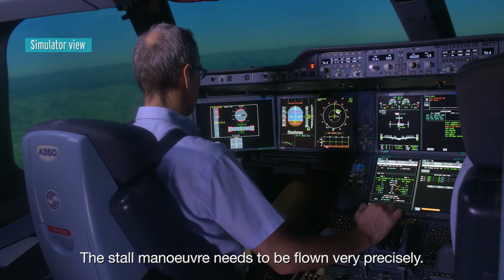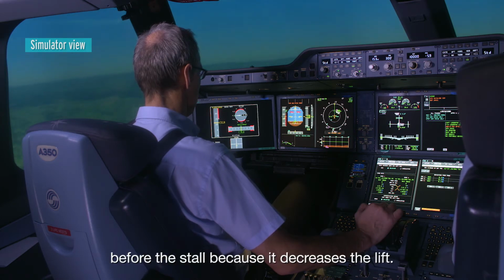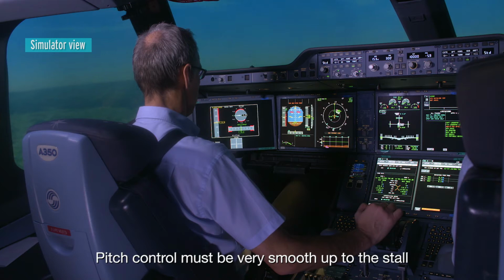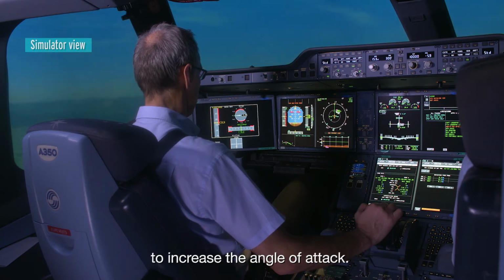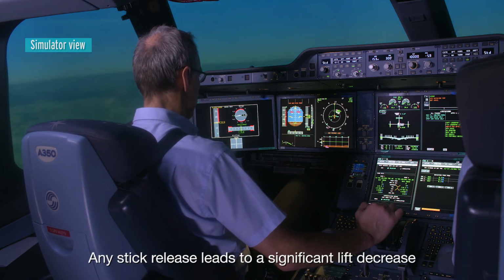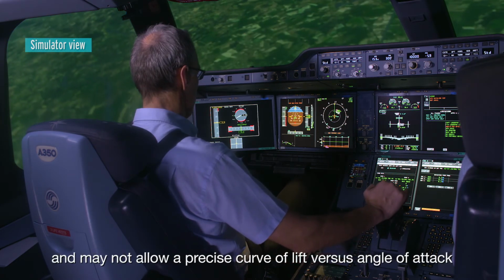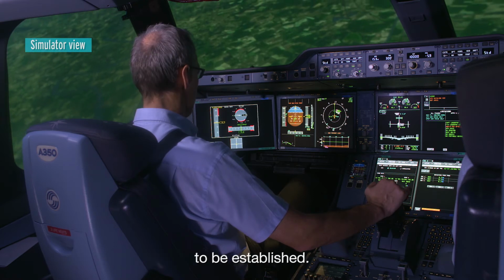The stall maneuver needs to be flown very precisely. Roll control is achieved without spoiler deflection before the stall because it decreases the lift. Pitch control must be very smooth up to the stall with a permanent backward displacement to increase the angle of attack. Any stick release leads to a significant lift decrease and may not allow a precise curve of lift versus angle of attack to be established.